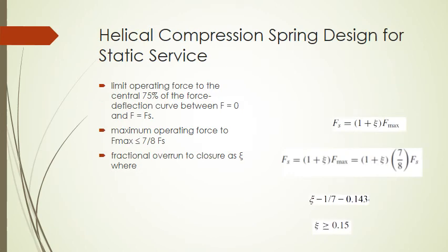Another property that is important for the spring design is to limit the maximum force on the spring. As you know, when you apply force on the spring, the graph between load and deflection is a straight line. We should achieve a straight line if we have a good design. To achieve this straight line and uniform behavior during load deflection, the application of force should be limited to 75% of the maximum force.